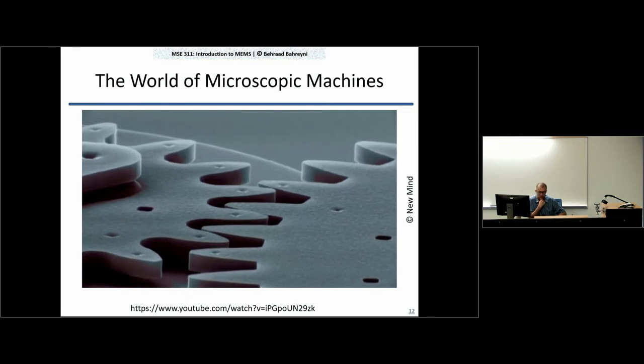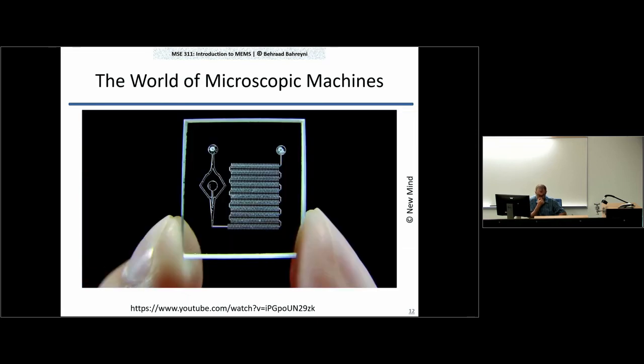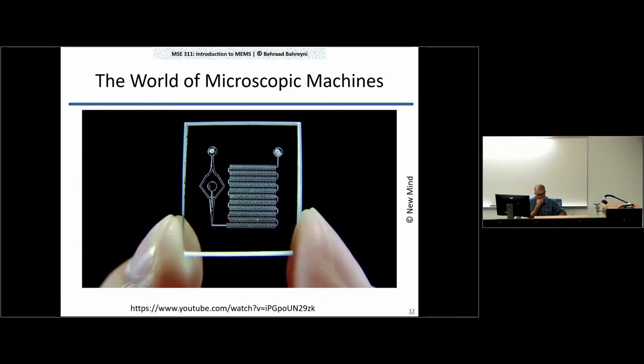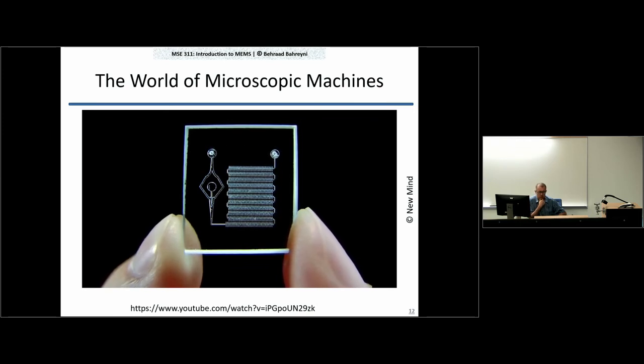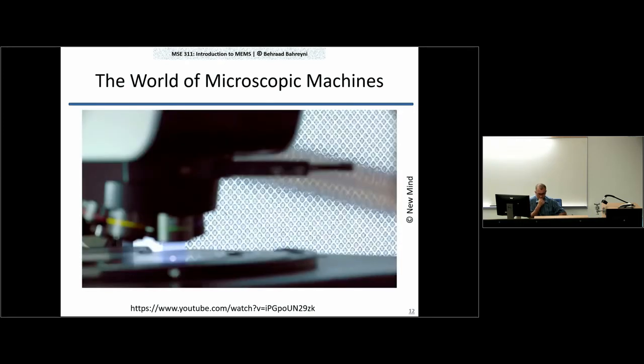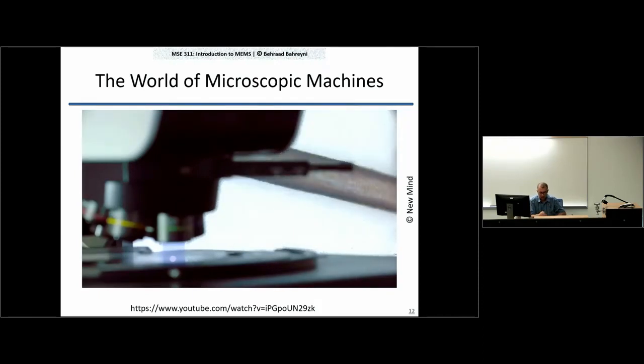High-aspect micromachining is one of the most attractive technologies for replicating microstructures at a high performance-to-cost ratio. Some common products micromachined with this technique include fluidic structures such as nozzle plates for inkjet printing and microchannel plates for disposable microtiter plates that are used in medical diagnostic applications. Let's take a look at those popular applications of MEMS devices we mentioned earlier and explore how they function.